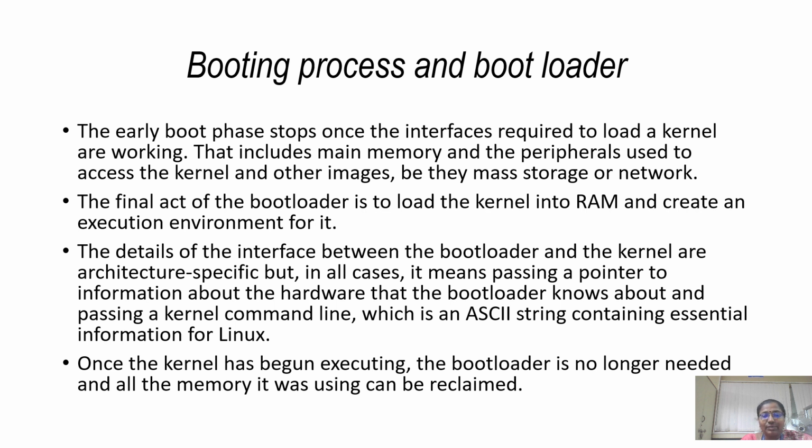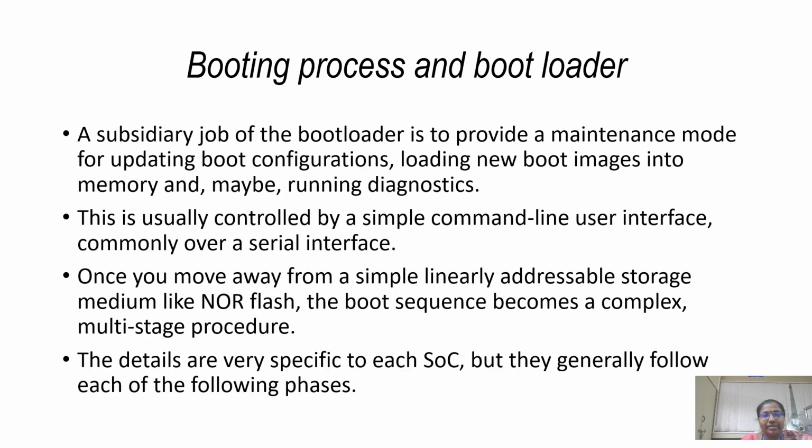Once the kernel has started executing, the bootloader is no longer needed and all the memory it was using can be reclaimed. A subsidiary job of the bootloader is to provide a maintenance mode for updating boot configurations, loading new boot images into memory, and running diagnostics. This is usually controlled by a single command line user interface, commonly over a serial interface.